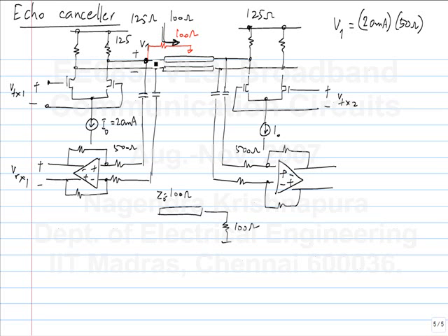Meaning if I apply a voltage between this point and ground, a current flows that says the impedance is 100 ohms. So I have to connect the impedance between that point and ground. So 20 milliamps times 50 ohms times the sign of VTX1. That's what appears here, assuming full switching.